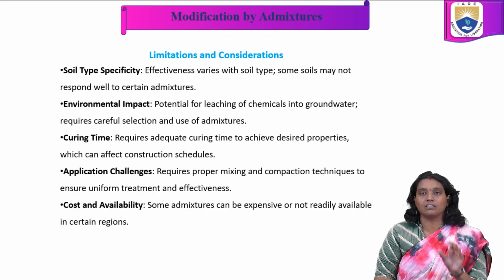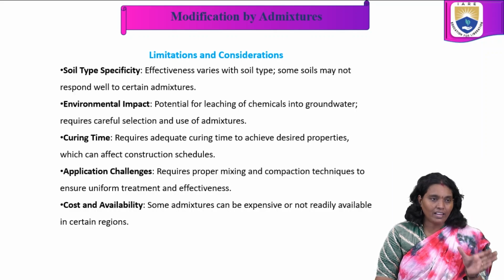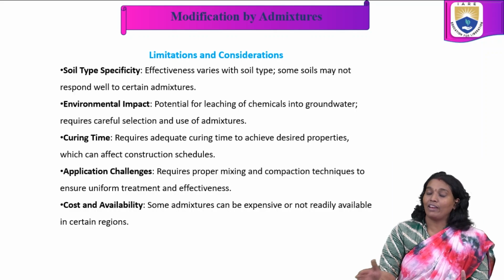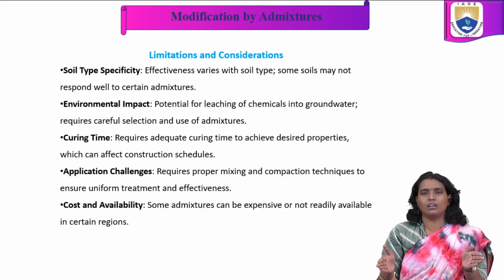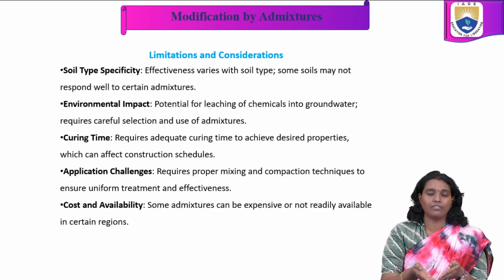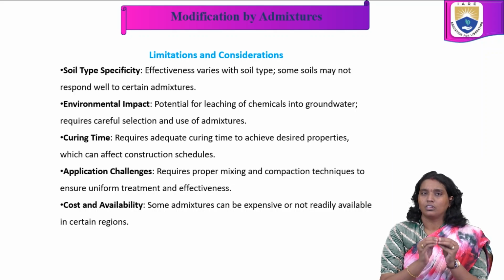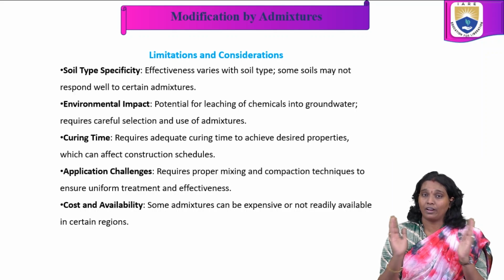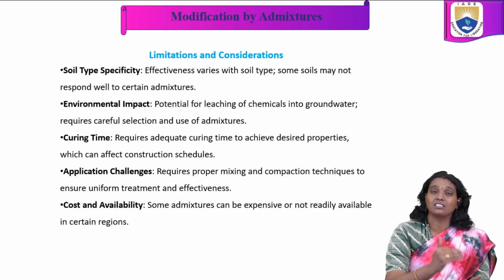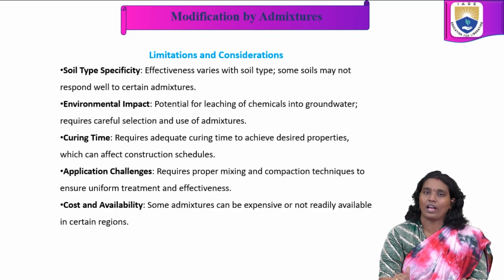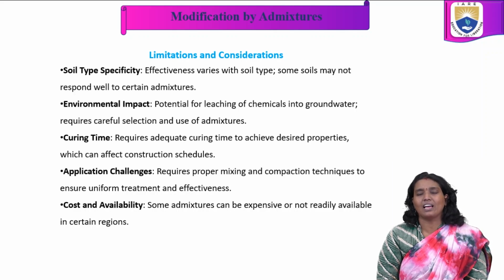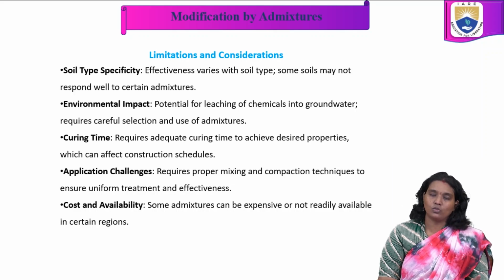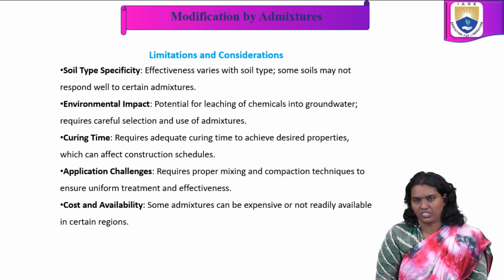So we have to analyze where it is required and when we are going to complete the work, and any alterations. If the curing time is required for a long time, it is going to affect the construction schedule, so alterations also we have to consider. That is also one of the limitations of soil modification using these admixtures.